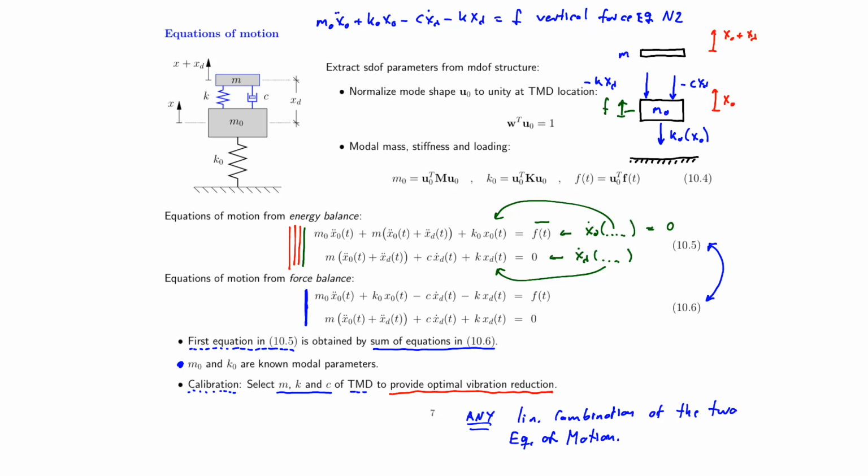For our 2 degree of freedom model containing the response of the structure and the response of the TMD represented by xd, the natural frequency omega 0 actually never appears as a representative frequency, because let's assume that you let c approach 0. In that case, the dashpot disappears, but you will still have a 2-DOF system with 2 natural frequencies different from omega 0.